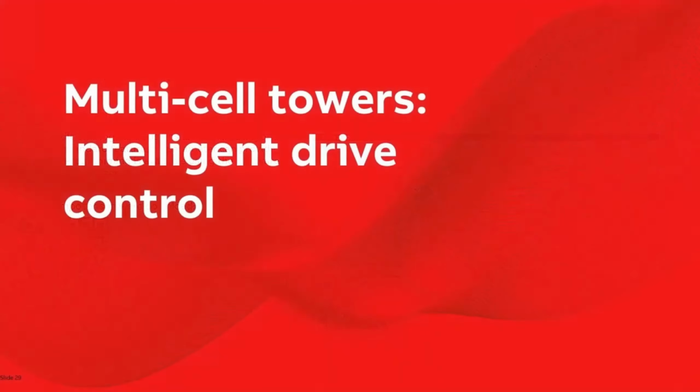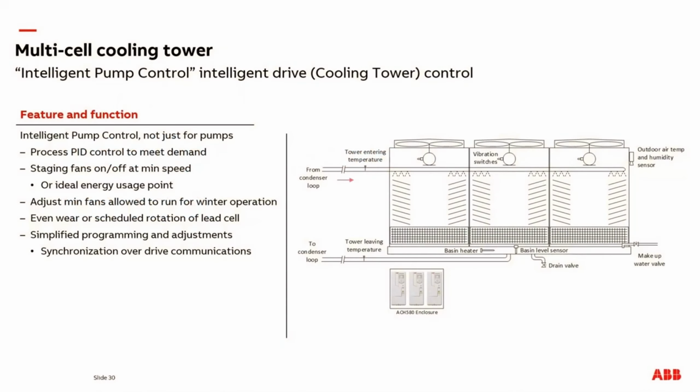Now let's cover the topic of multi-cell towers integrated with an intelligent drive control. The ABB ACH580 series of drives includes a multi-pump and fan feature called Intelligent Pump Control. Don't let the name scare you away from the idea. This multi-drive communication function is just as capable for fans as well as pumps. With process PID control,